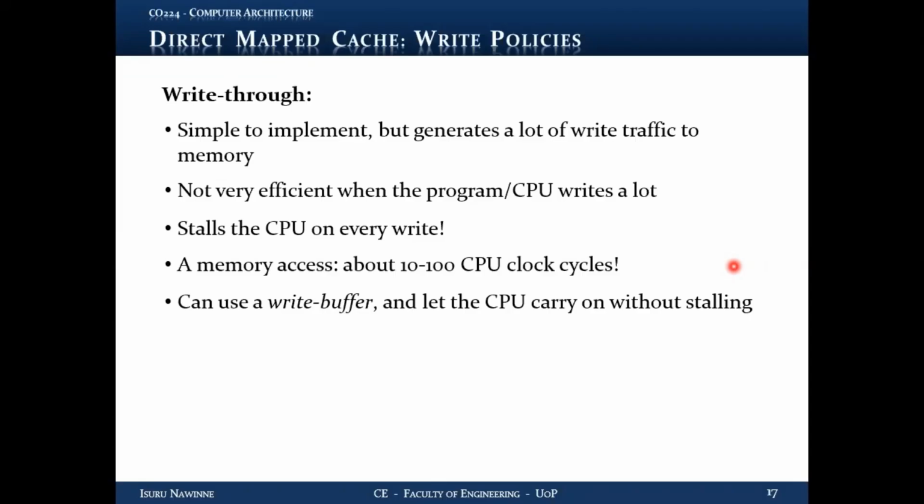Depending on the size of the buffer, you may be able to put a number of requests in the buffer, and the memory can handle these write requests at its own speed. As long as there are write requests in the buffer, the memory can finish the current write request and then take the next request from the first-in-first-out queue.